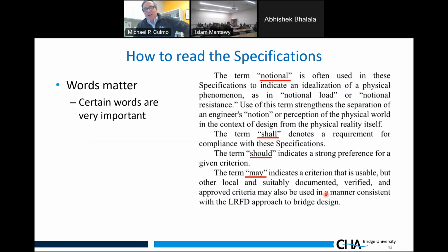The terms shall, should, and may are really important. Shall denotes a requirement, meaning if something says shall, you have to do it. If something says should, it's a strong preference and you probably will do it. If it says may, technically you have the option. You don't have to use that provision. And I'll give some examples in a minute.